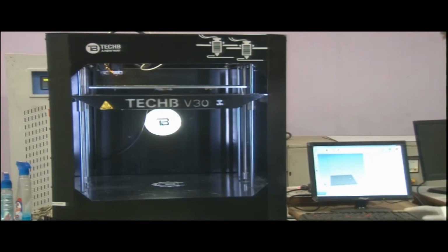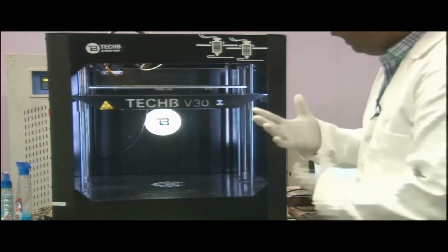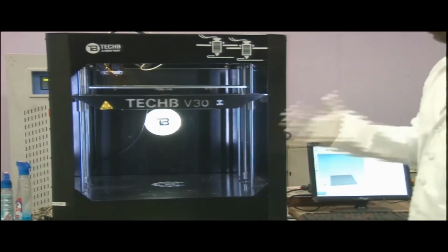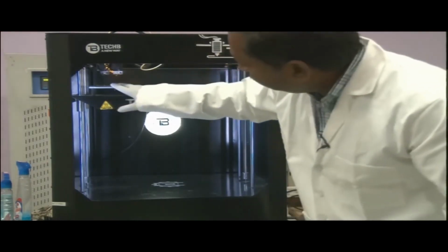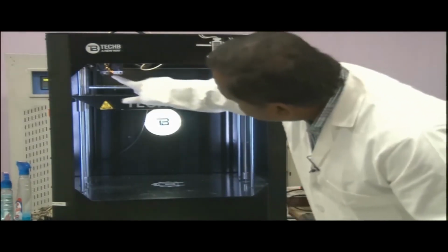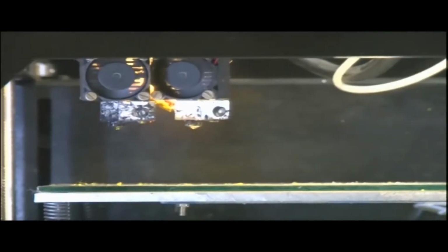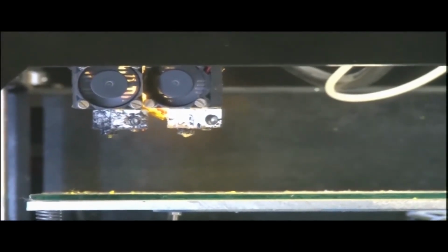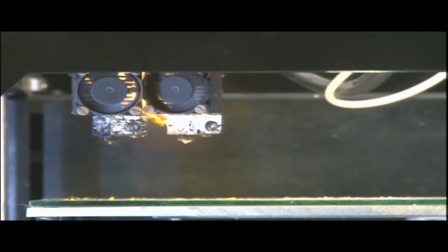When we start machining, that is, try to fabricate anything in 3D printing, we have to take care of a number of things like cleaning of the bed, cleaning of the head nozzles, and proper cooling as well. For cooling, we have to check that the two fans just above the head are running. So whenever we start fabrication on this machine, we have to take care of a few things like proper cleaning,